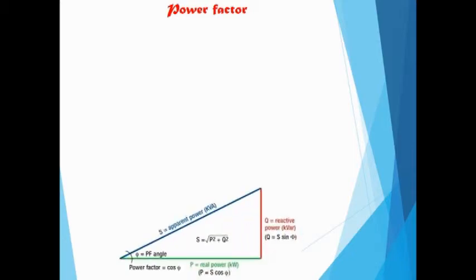Now, so you can see why we need to improve our power factor. To improve our power factor, that means we bring basically this blue vector or phasor all the way down to, or as close as, the green vector. Bring it down to the green, the horizontal axis. So you are basically paying for what you're using. You don't pay this much for what you don't use.